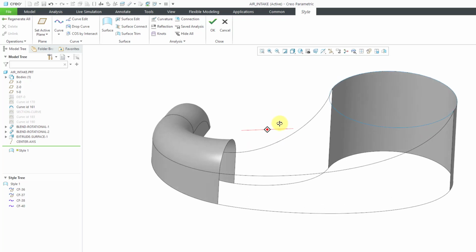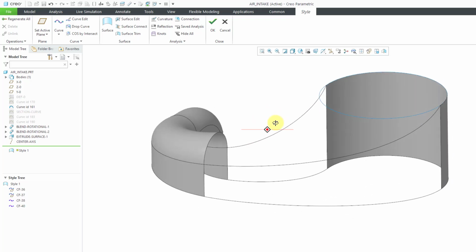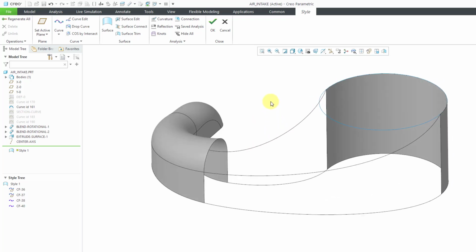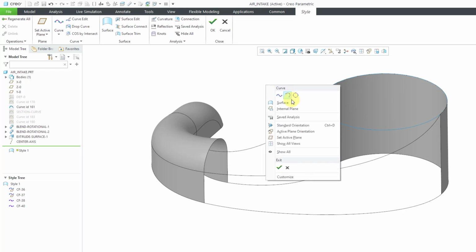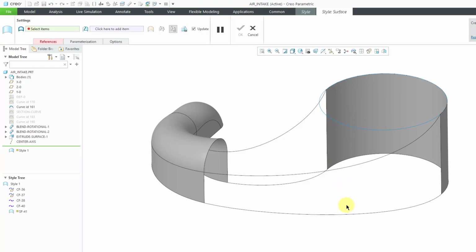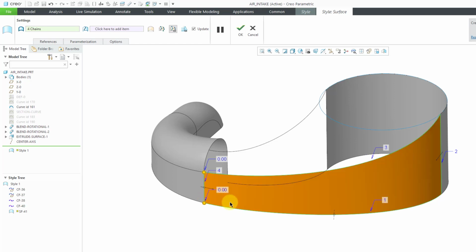Now we can go about seeing the shape of the surfaces that we can generate here. Let me right mouse click and hold and choose surface. And I will select the first boundary curve, and then I'll hold the Control key, not the Shift key. I will hold down the Control key, grab this edge, and then Control and grab this curve, and then this edge.